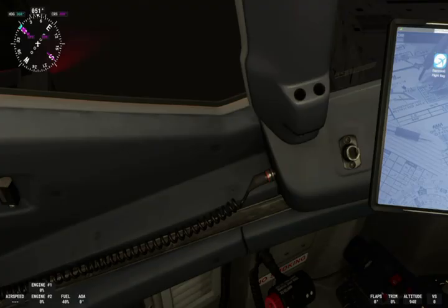We'll expect clearance to 34,000 feet. Weather at departure is clear. No significant changes since dispatch. The departure runway length is 9,000 feet. Using 2-9er thrust. V speeds are V1 150, VR 151, V2 155. Acceleration altitude is 1,500 feet.